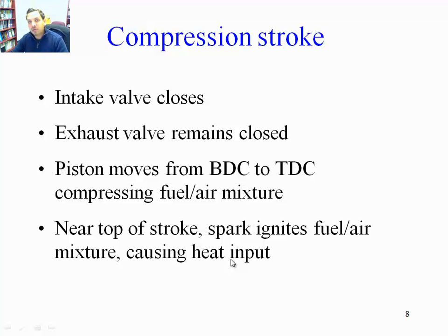If it's a diesel cycle, there's no spark. So the compression itself will be enough to create the combustion, or trigger the combustion. So that's why the fuel is not mixed. In the case of diesel engines, the fuel is not mixed with the air before the compression stage, because otherwise you'll have pre-combustion as the piston is moving up, causing all sorts of problems in the generation of power. So what you do is wait until the piston gets all the way up, and at that point you inject the fuel, try to mix it as homogeneously as possible with the air, and then let combustion take place as the piston is moving down, not as the piston is moving up.